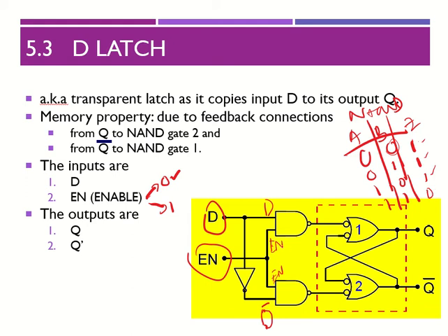So over here, let's say your enable is 0, and over here 0. Anything with 0, you're going to have 1 over here. And anything with D bar, let's say D, anything with 0, you're going to have a 1 according to your NAND truth table. So 1, 1 will go in, and after it reaches this one, this will give you 1, 1. If you look back at your latch previously,